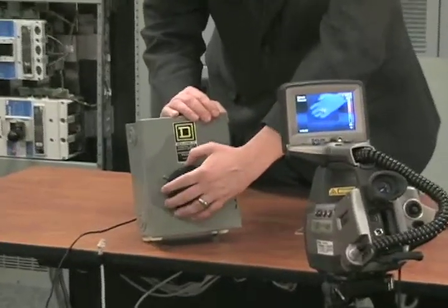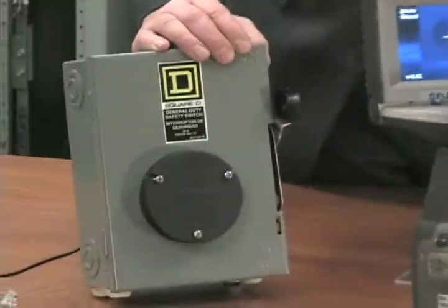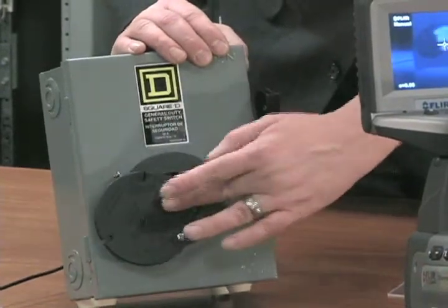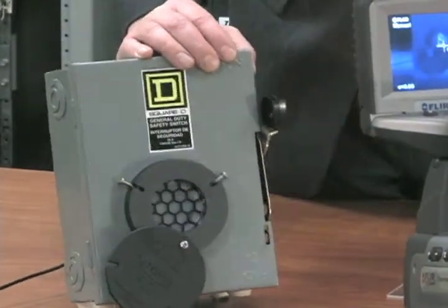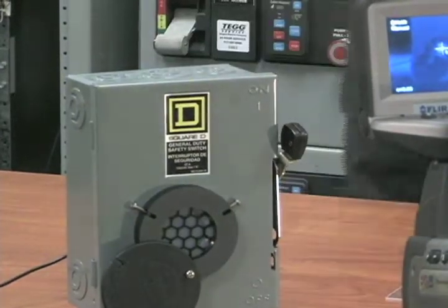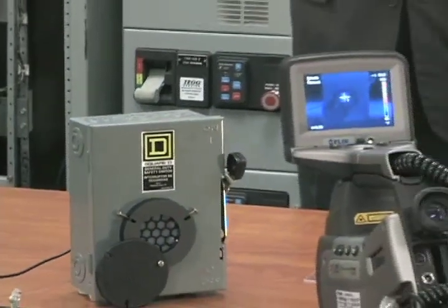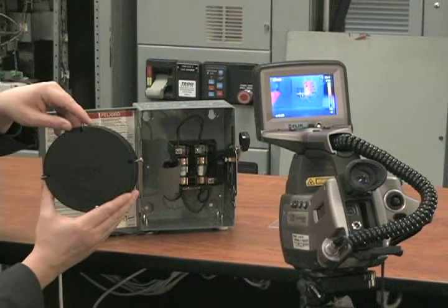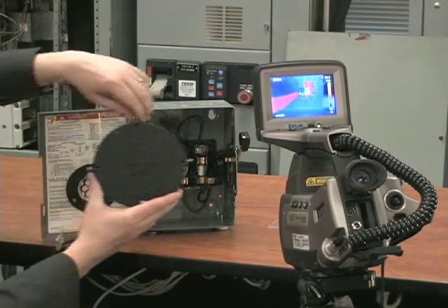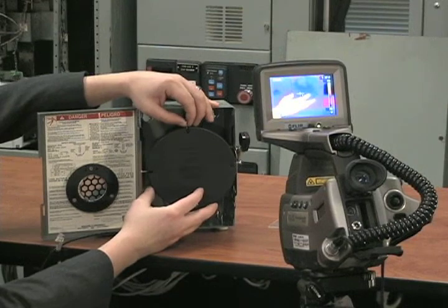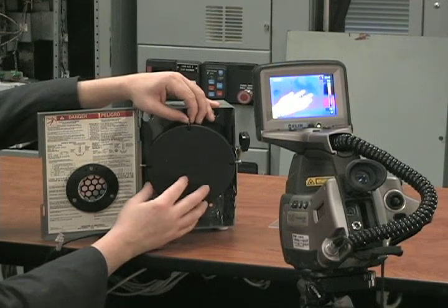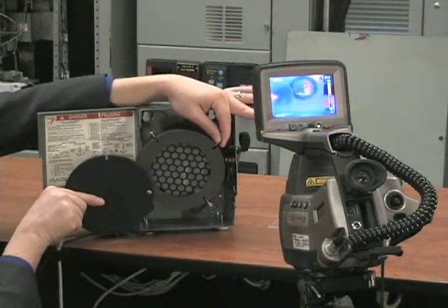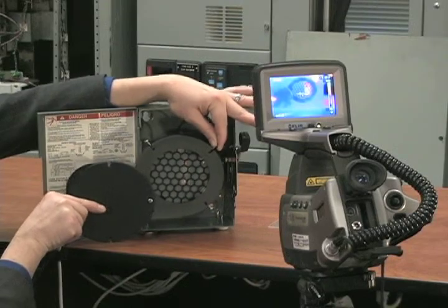So when performing an infrared inspection, normally you'll come up to the cover will be locked shut. The infrared technician will open up the cover and be able to take the camera and look through the window at the actual issue. The next thing I'm going to do is physically demonstrate how this infrared camera can see through this window. I'm going to use a slightly larger infrared window so that it shows up easy on the video camera. But here's the infrared lens with a cover installed, and then opening up the cover, and the camera can see through the lens.